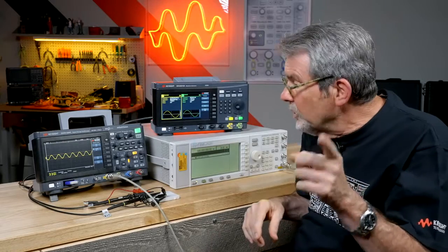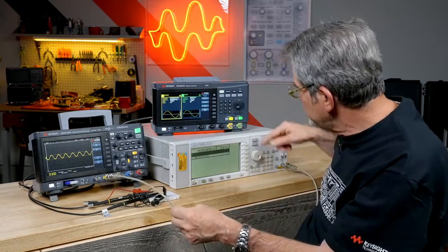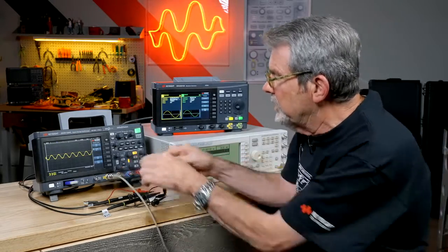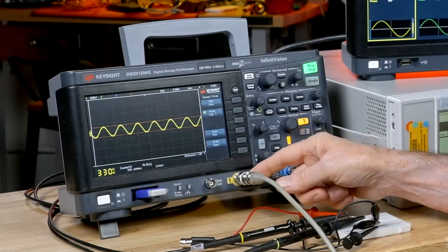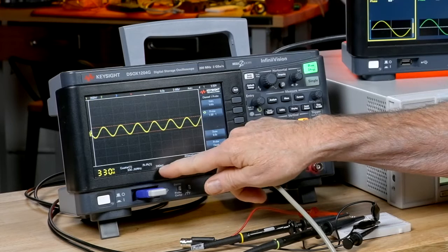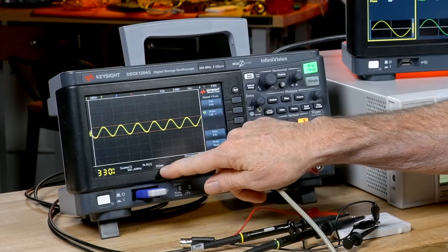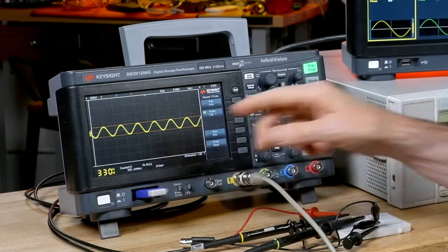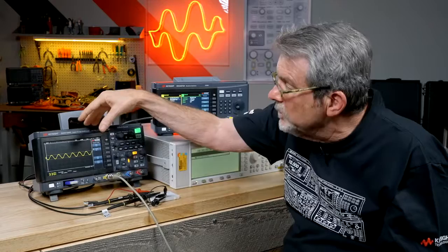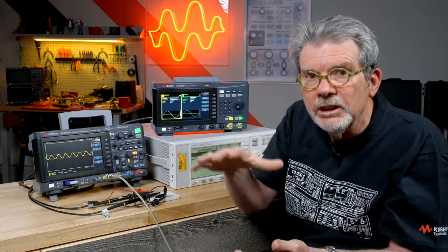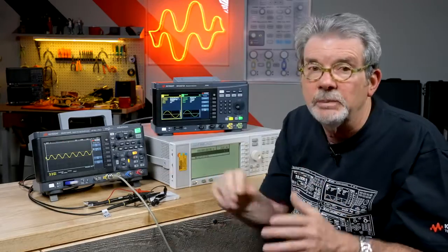Now, one thing I want to make sure you're aware of, the output signal, the signal coming out of this BNC, is still 1 volt peak to peak, even though it says it's only about a 1/4 volt peak to peak right now. This is constant. What's happening is the analog hardware on the input of this oscilloscope can't handle the higher frequencies and it attenuates it. It can't pass them.